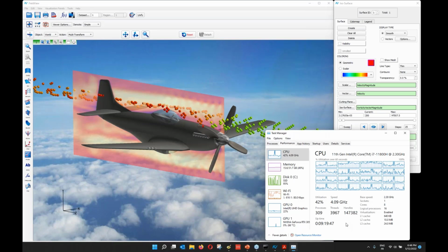So that's for parallel. For most of the solvers that do export to the FieldView heavy-units format, the partitions from the solver are preserved. Sometimes you have to be aware of how to do it, so if you have any doubt, please don't hesitate to come to our support team or ask Raja or myself for how to do that. And for a lot of the structured formats as well, we have options for using the multiple grids for parallelizing our operations.